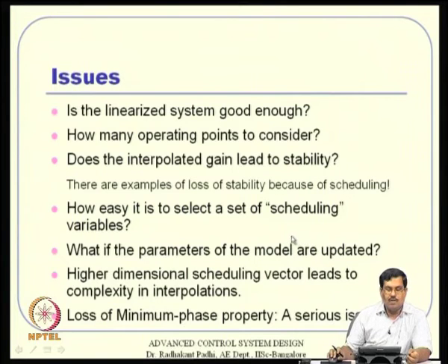That concept we will see in dynamic inversion anyway. If you are designing a tracking controller, for example, pilot command implementation is nothing but a tracking controller. The pilot gives a command and your control system has to track that. In those situations maybe tracking itself will be okay, or suppose you want to climb, height climb is probably okay, but the lateral dynamics may go unstable.